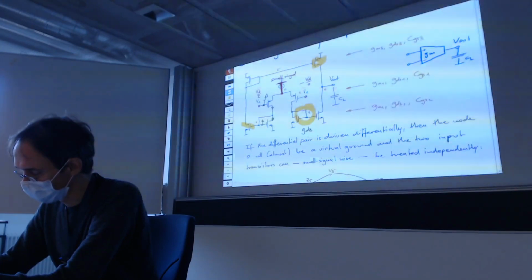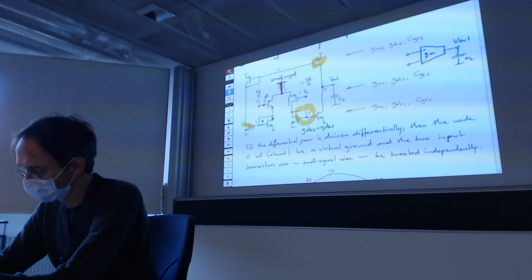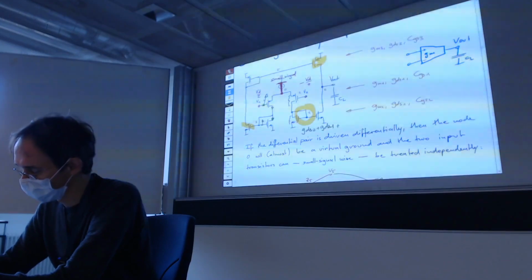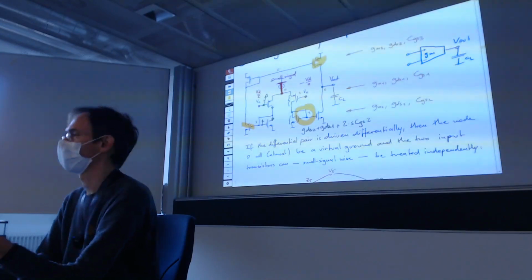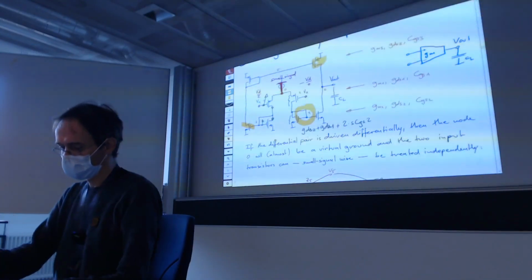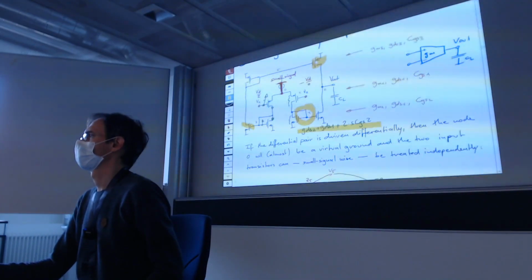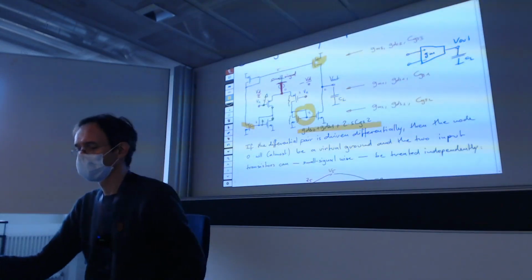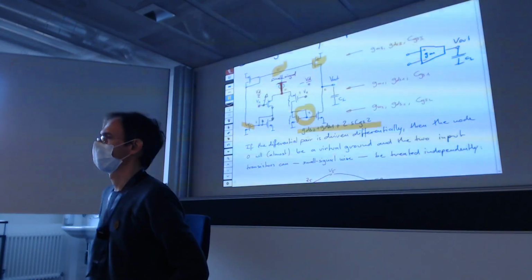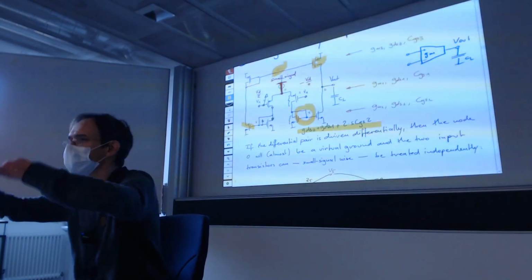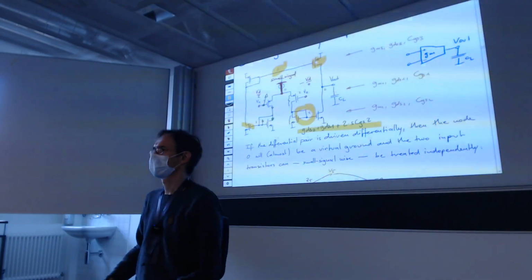At this node, I have a GDS2 plus a GDS1. These are these two resistors here, plus the two gate source capacitors of those transistors. They are both CGS2. And I can just look at this expression, and I already know where one of the poles of my circuit are. And if the pole, like the one up here at the node 5, is only in one path, then yes, you also get the pole, but you also get the zero at twice the frequency. And like this, an experienced analog designer will be very fast in estimating what happens.